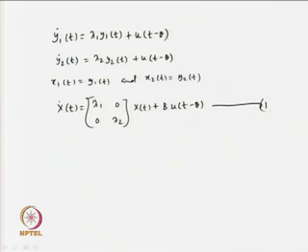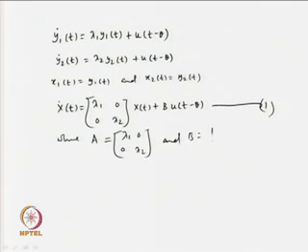So, this is how we obtain a state equation form of representation of the dynamics of a real time system, where the A matrix is A equal to [lambda 1 0; 0 lambda 2] and B is equal to [1 1] for the second order case.